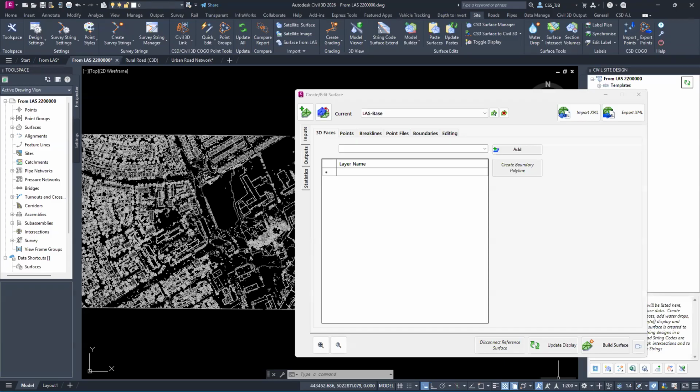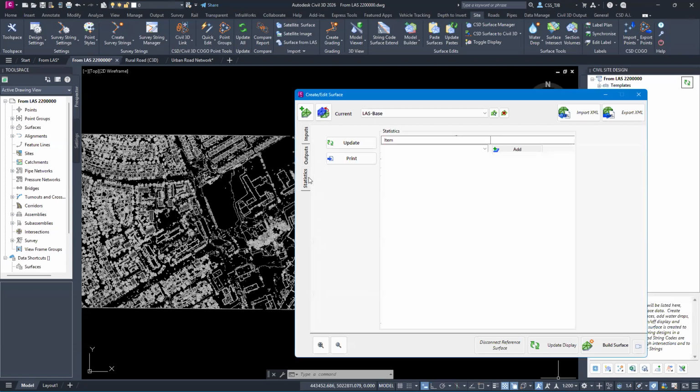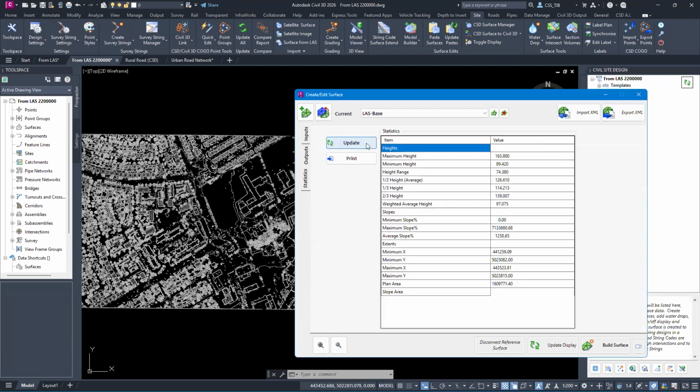So, as I said, this is the full 2.2 million point file, but if I actually look at the numbers in it, it has only built a surface of about 1.7 million points. So the surface is far more detailed than the previous one. But as I said, this is the adaptive, sorry, decimate, and it kicks in automatically. You don't get control over it. The software just does it to maintain the system integrity. But that's the difference between the two surfaces.